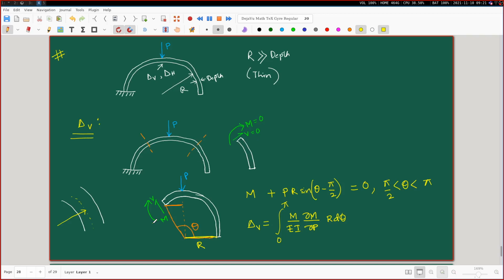So earlier, when we did not have a force at a point where we wanted the deflection, we artificially introduced a force there, and then we proceeded by the dummy force method or the fictitious force method.